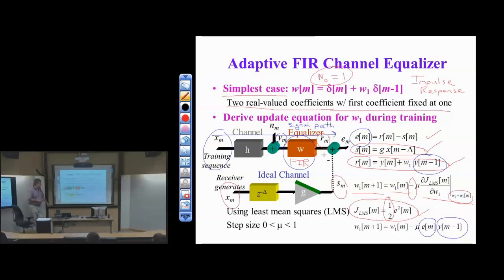So the equalizer here can handle linear, time-varying effects. The adaptive version, it's huge. And it works fine in the presence of noise. The least squares equalizer has another problem in that it can amplify noise if you're not careful. It depends how you do the least squares equalization.